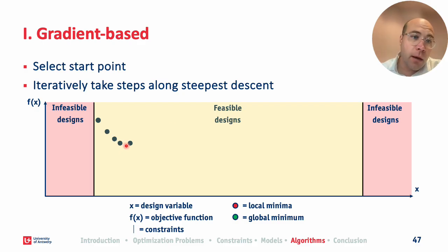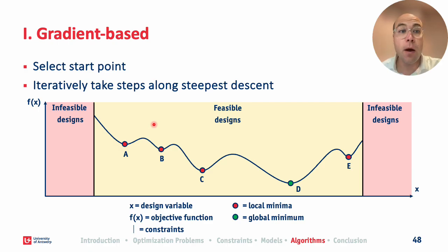Whenever it sees an increasing gradient, it knows, okay, we passed the lowest point. This will be the optimum. In practice, the curve can look like this, but it's very important: an optimization algorithm does not know this. An optimization algorithm repetitively runs your model, be it analytical or simulation, gives design parameters, and checks the value of the objective.